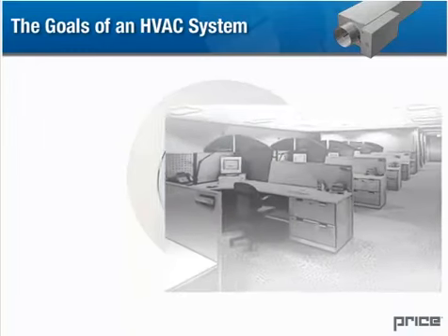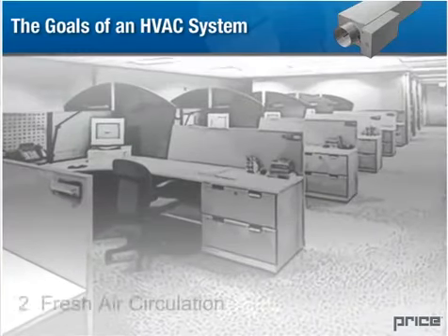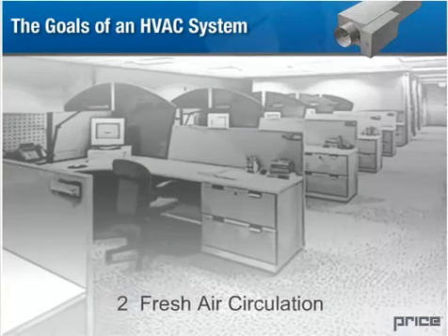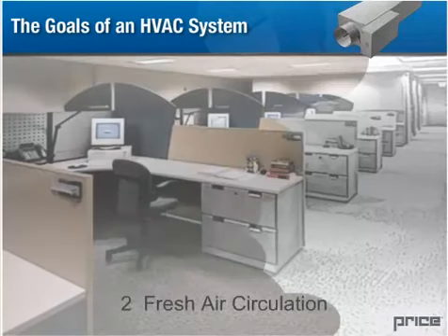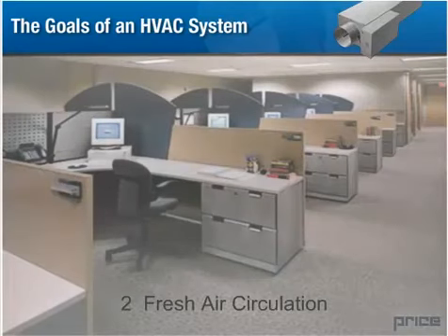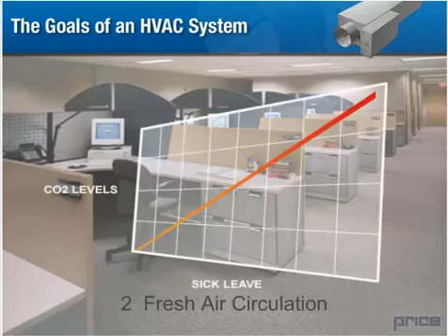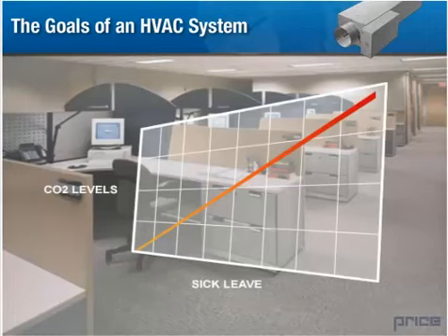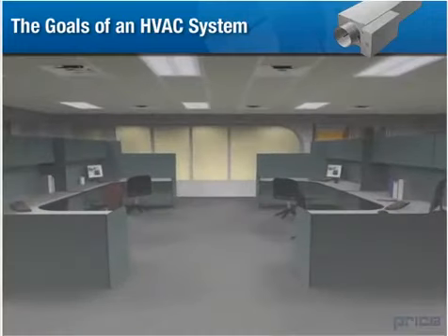But equally important, the HVAC system must keep occupants comfortable by supplying fresh air to a room. If we introduce a significant proportion of fresh exterior air and alleviate carbon dioxide buildup, occupants experience better health and performance gains. Studies have shown a direct link between CO2 levels and short-term sick leave in office workforces. However, our concerns regarding the HVAC system and occupant health do not end here.